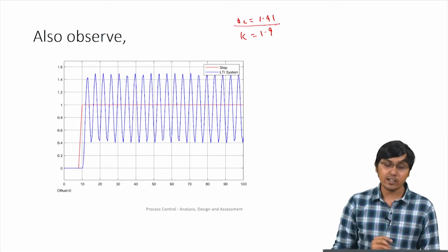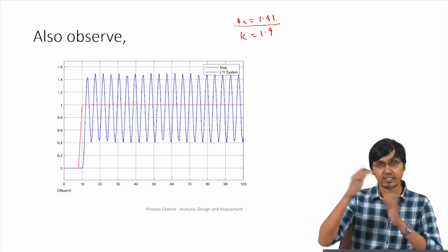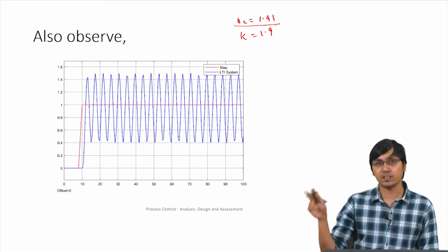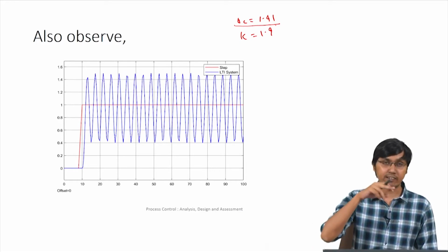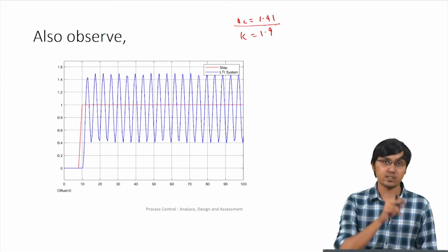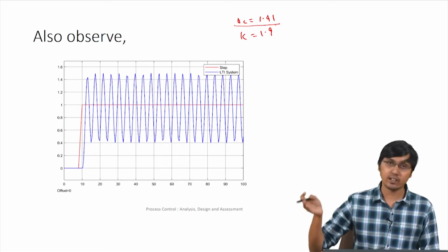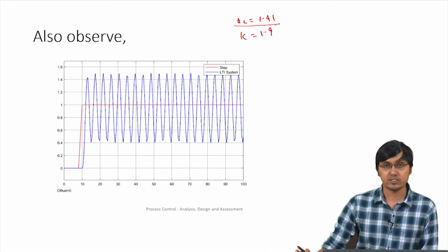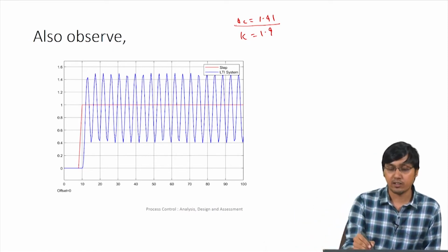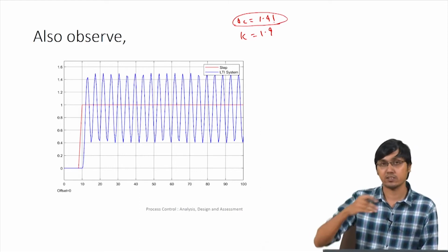If you ask why, it is because of the Barkhausen rule: the sine wave goes around the loop in phase. At that frequency it comes around the loop in phase, and it has a gain equal to 1. So it keeps oscillating at this particular omega c, at which the sine wave is in phase around the loop.